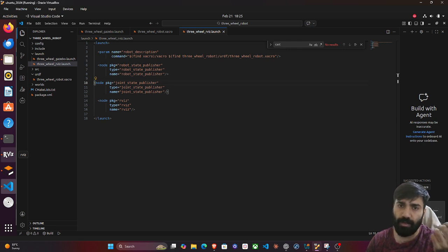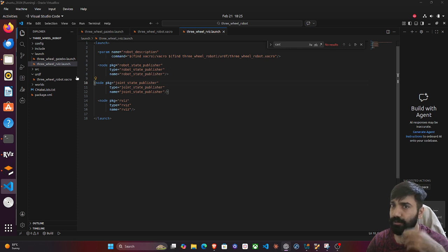First and foremost, we require to have ROS1 installed. You can mkdir the catkin_ws, okay. After that, we require certain packages to be installed. So you can use catkin_create_pkg with the package name, like first would be the folder name, that would be trivial robots with roscpp, rospy, std_msgs, and gazebo_ros. Okay. Then once you hit that, you will be able to see this kind of folder structure.